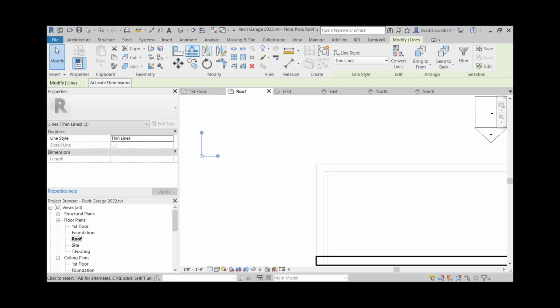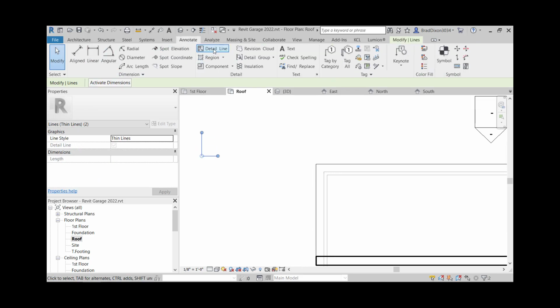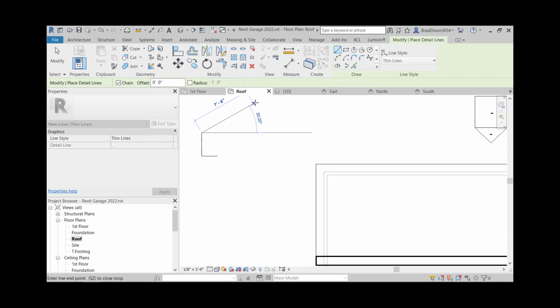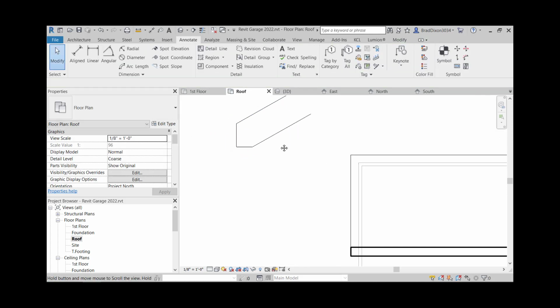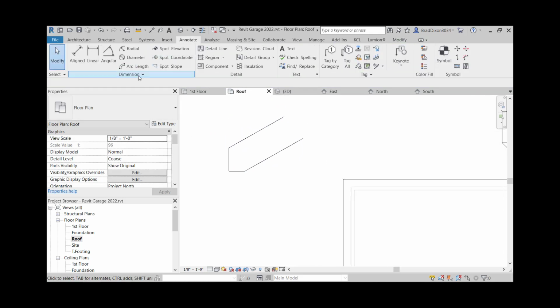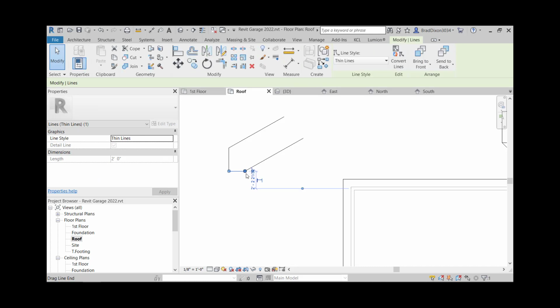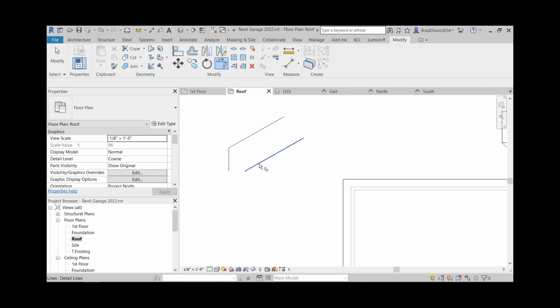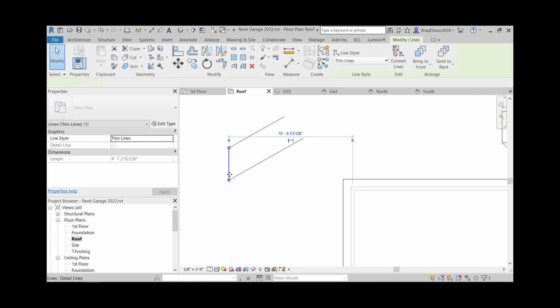That's kind of hard to see without actually cutting that off, but this is basically what the rafter would look like right here. So that would be a 2-cut plumb. And if I just had these two joined together like that, that would be a plumb cut, or one cut plumb. And the problem with this is my fascia ends up being very big, very long.